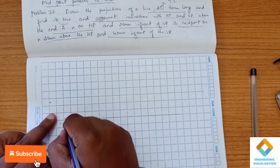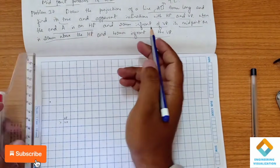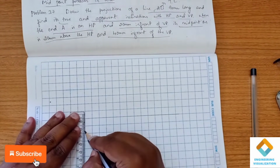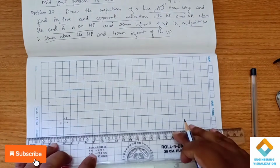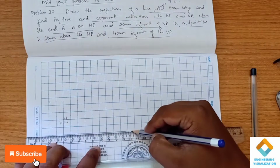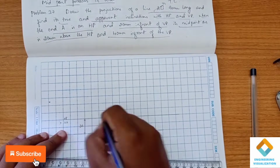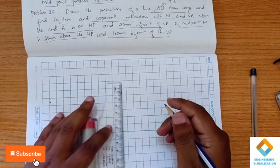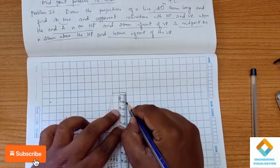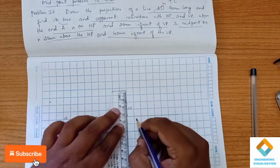So X, VP, HP. So end A here, you can see that end A is on HP and 20 mm in front of VP. So 20 mm in front of VP. So here we are going to draw a locus line. Okay. So this distance, it is 20. Okay, for the midpoint we have 20 mm above HP, 20 mm above HP here, and 40 mm in front of VP.